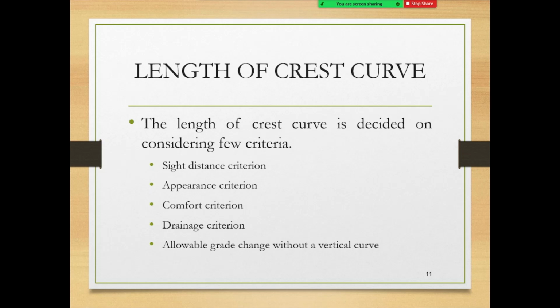And then the length of the crest curve is determined using the following criteria. The length of a crest curve is decided on considering a few criteria. What are they? Sight distance criterion, appearance criterion, comfort criterion, drainage criterion, and allowable grade change without a vertical curve, right?